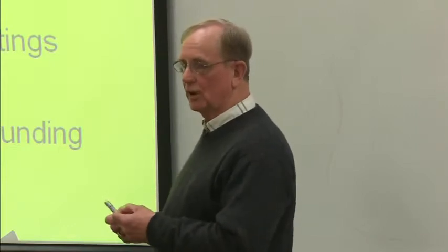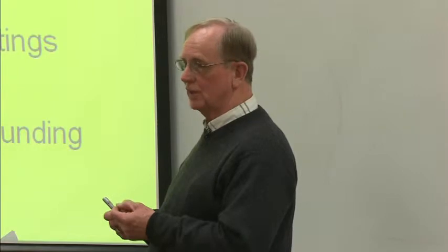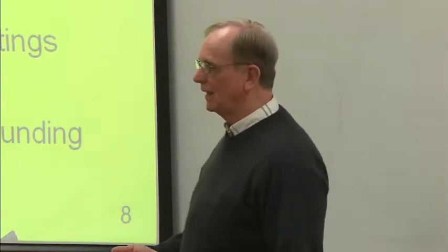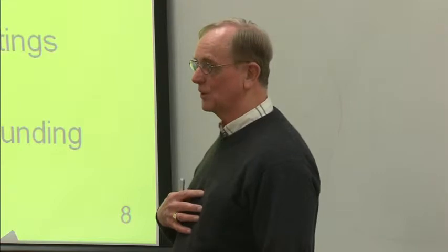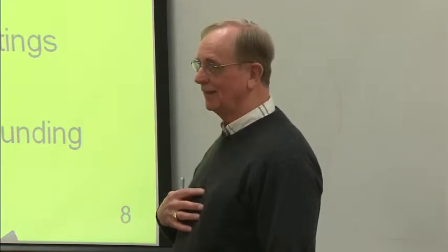And that's what a ground fault circuit interrupter does. It looks at the current on the two conductors and compares them. And if there's a difference of 5 milliamps, it turns off the circuit. Reason for that? You can go into defibrillation at just over 5 milliamps. Your heart quits beating properly. And you can go into cardiac arrest.